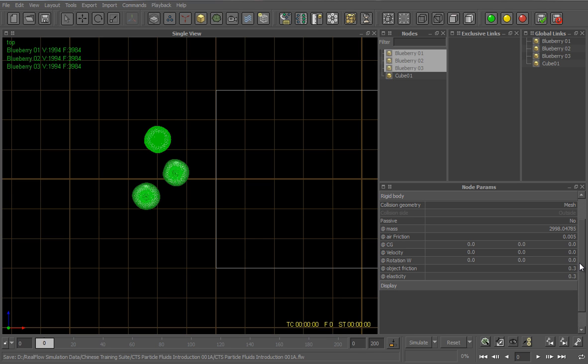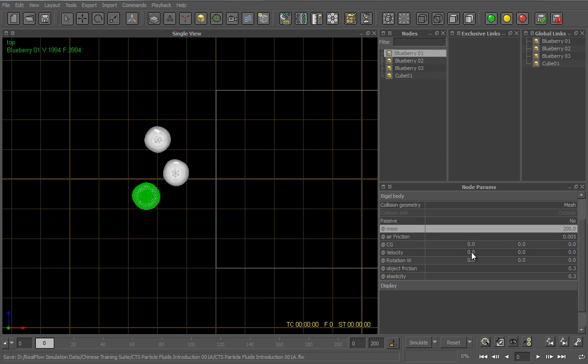Mass is a very important parameter because it strongly influences the strength and height of the splashes. Depending on your 3D software and scale, the default mass can be very high. Values between 150 and 300 should be sufficient. Another parameter that has strong impact on the fluid-body interaction is velocity. Even very small objects can cause huge splashes when they are fast enough. For our commercial, we need rather moderate splashes because we do not want to see a torn look with lots of fine drops.